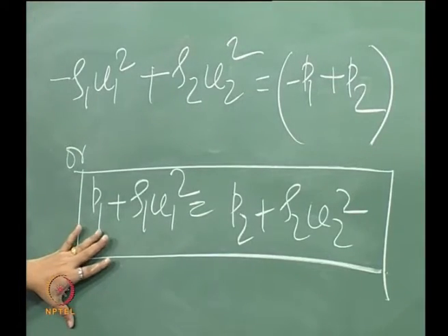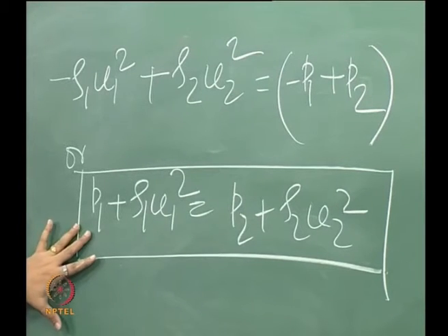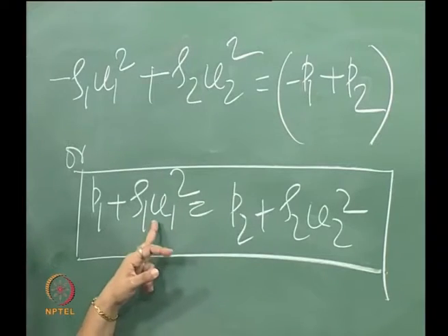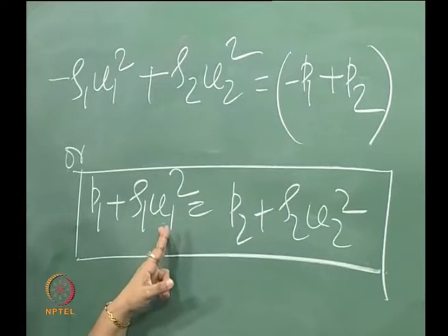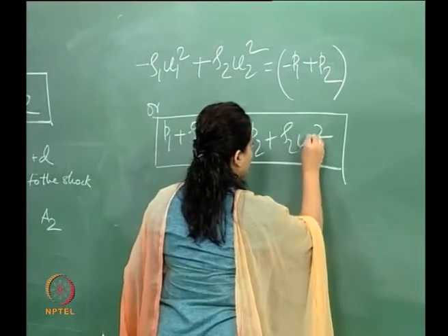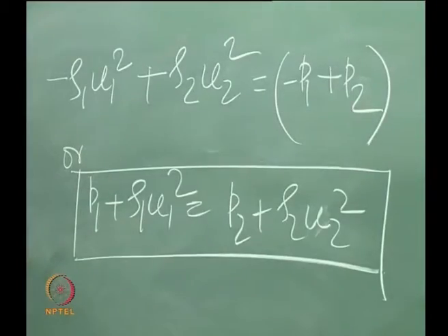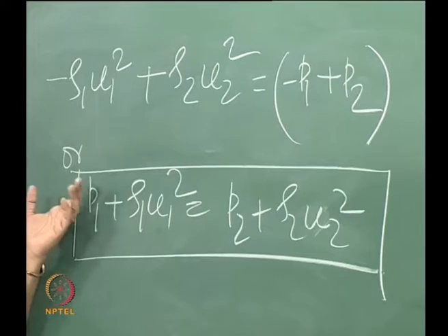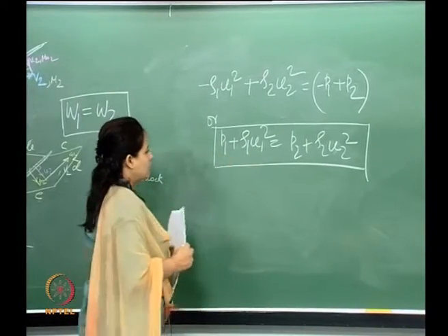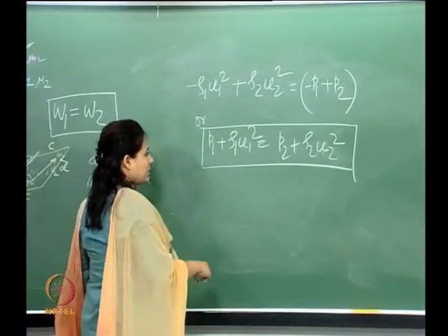And again you can see that what we are using here is the normal component of the velocity across the oblique shock. Therefore, what we got from continuity and from momentum with the normal component of the velocity is the same as what we got for a normal shock. So let us complete this and write out the energy equation.